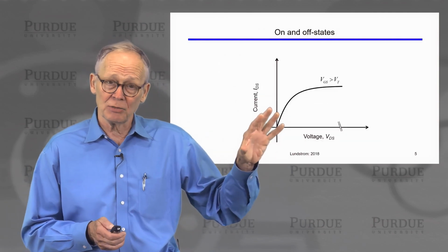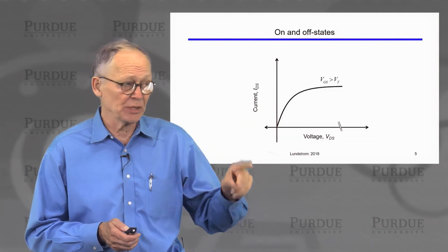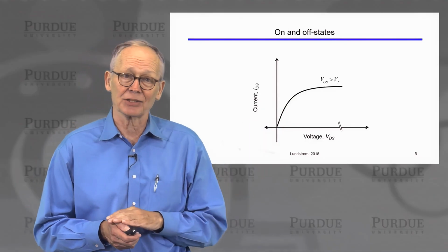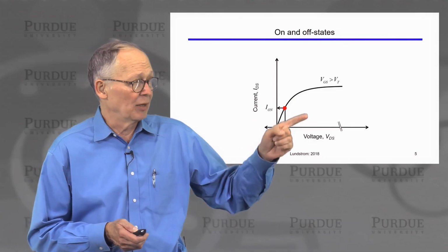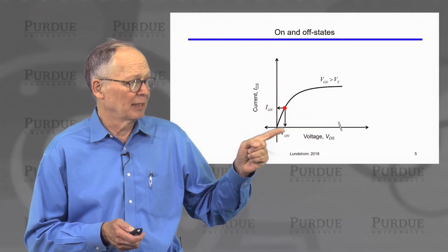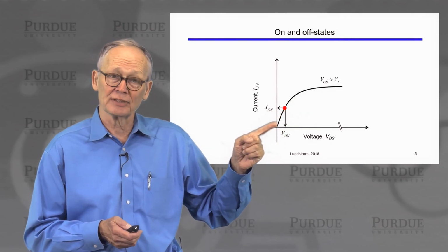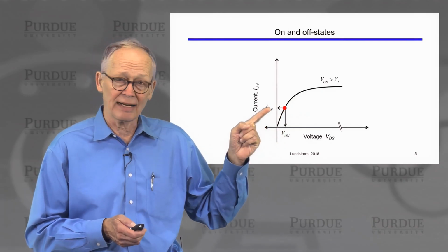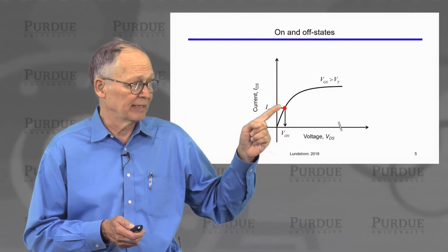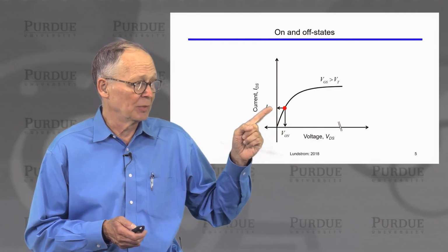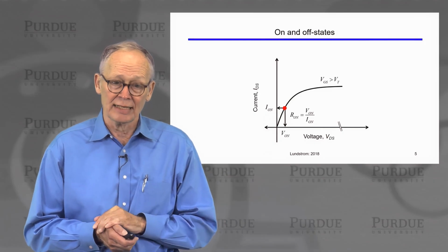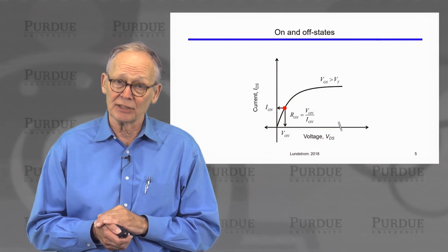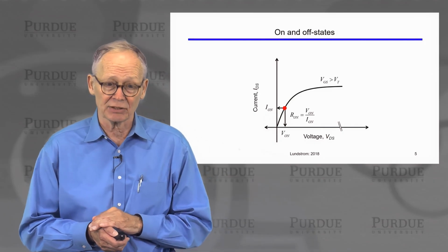Okay, so we're going to use the MOSFET as a digital on-off switch. MOSFETs have IV characteristics, output characteristics that look like this. We would like to be operating at some low voltage when the switch is closed and get a high current that flows. So the key considerations will be how much current flows at a particular on voltage, and we will be operating here in the linear region of the IV characteristic.